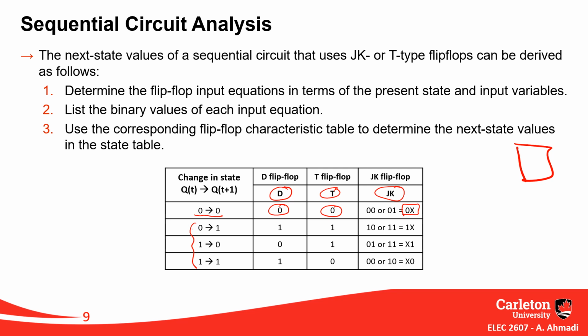In a circuit like our example, how many flip-flops do I need? 3 flip-flops, because my states were 3 binary digit states: S0, S1, S2, and so on, to S6 or S7 or whatever number of states you have. Now, I want to do the same thing, following the same strategy.